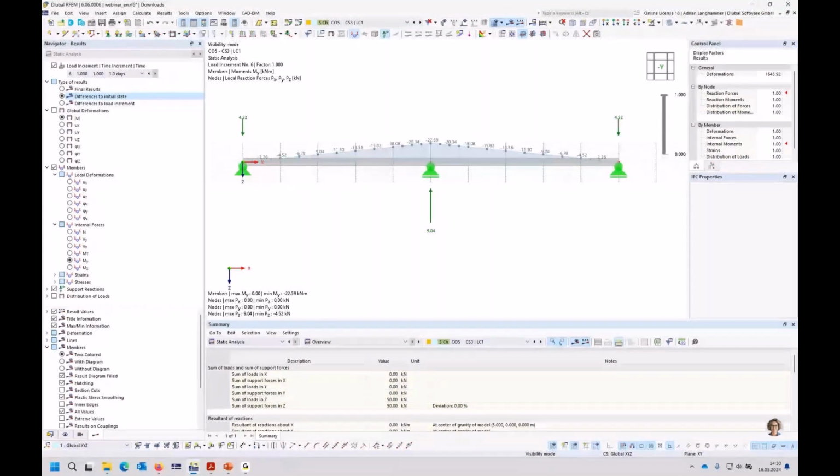The TDA, time-dependent analysis, uses here a rheology model, which works based on so-called Kelvin-Maxwell chains. This means that, for example, due to the consideration of creeping, there is not only a simple reduction of stiffness, like it could be also done in a more simple way to consider creep. Here there are used elements